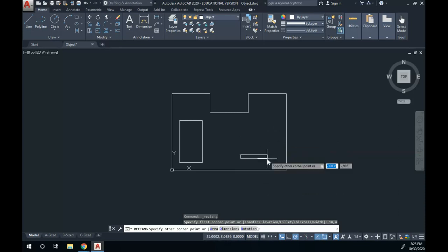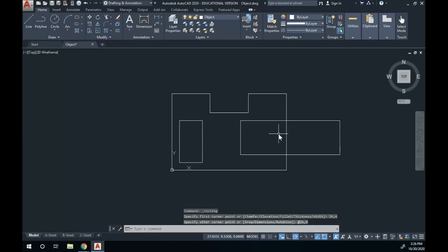There's a couple different ways I can do that. The way that the textbook is probably going to ask you to do it: if I'm going 18 units to the right in the x coordinate, and I want to go another 8 units to the right, 18 plus 8 gives me 26. So I'm going to type 26, tab over, and if I'm at 4 units for the y-axis, I need to go up another 5, so that y coordinate is going to be 9. So I'll type 9. I'll hit enter. Oops, something happened there. Oops. Let's redo that one.